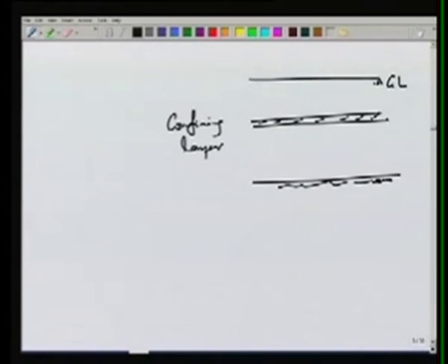So in this confined aquifer, we can look at an elementary volume and see how the head change affects the amount of storage and the amount of water which is coming in. And then by balancing these two, we can derive an equation which will tell us how the head is changing with time and space. So the spatial and temporal variation of the head can be obtained by the continuity equation.